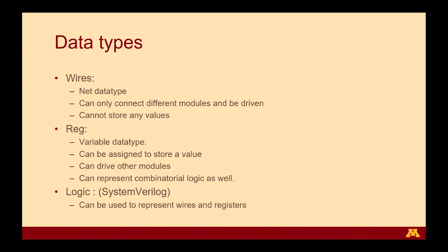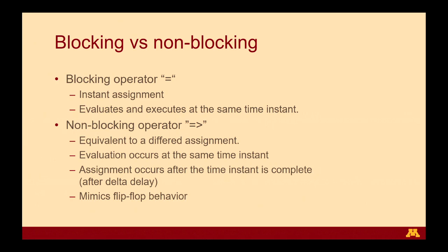All right? So another important aspect which Verilog covers, and which essentially models all of digital design, is the blocking statement and the non-blocking statement. As the name implies, a blocking statement just states that all execution is blocked till this statement completes.